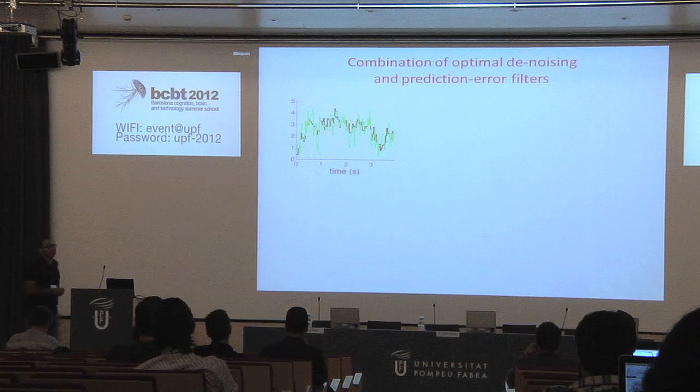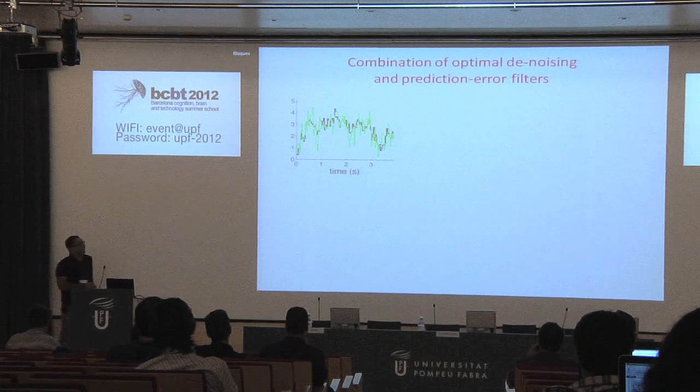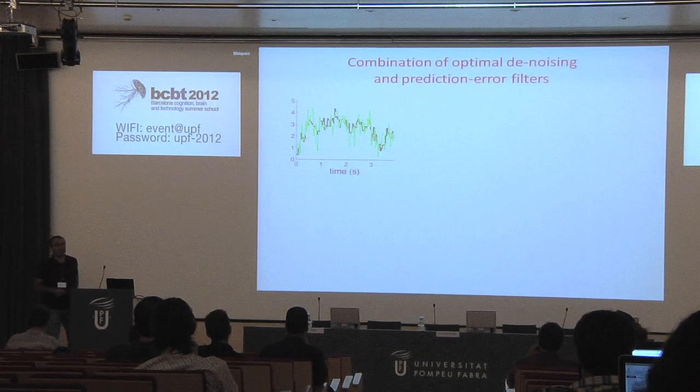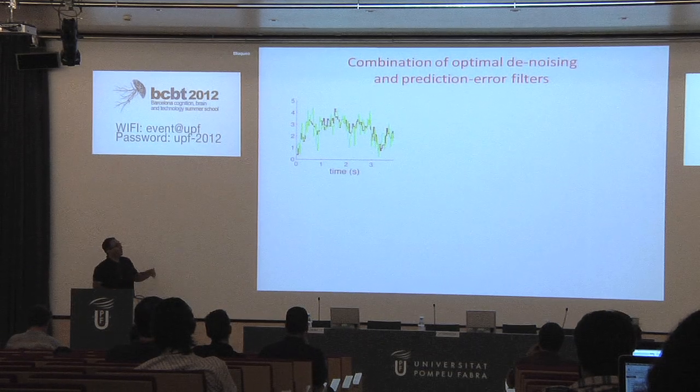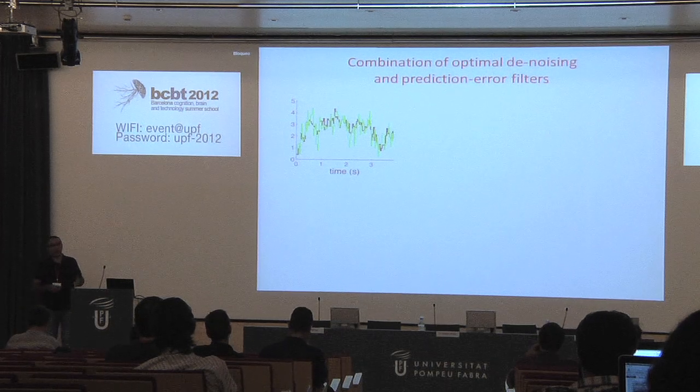Why should we think about such kind of stimulus? Well, for example, because real signals usually come with a lot of noise components, and the noise presumably is uncorrelated. And so at low signal-to-noise ratios, the dynamic range of the signal will not be reduced by the circuit, but could actually increase.